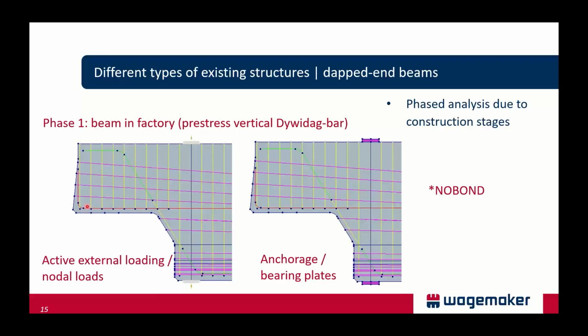During that phase, the vertical Dywidag bar, the pre-stressing bar, was stressed by nodal loads as well. And in the subsequent stage, the anchorage bearing plates were attached to the Dywidag bar using a master-slave formulation of nodal displacement. And here we see some details of the structure itself.